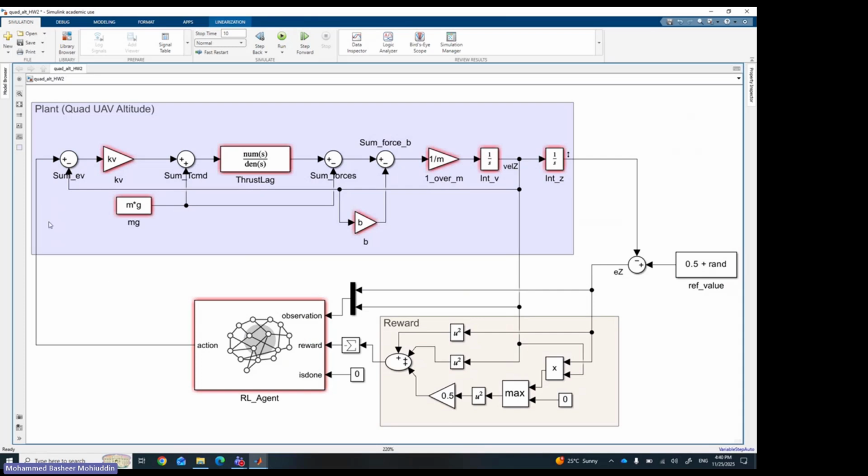Then you have the actual Z dot coming from the system, which passes through the error and then goes through this block, which can be considered a proportional controller, a P controller. And then you have the plant dynamics, obviously. In these plant dynamics, this is the aerodynamic effect, this is the thrust force, everything comes together. Then you divide by M, which means you're taking basically the specific thrust. And then again Z double dot, Z dot, Z. So clear till this point?